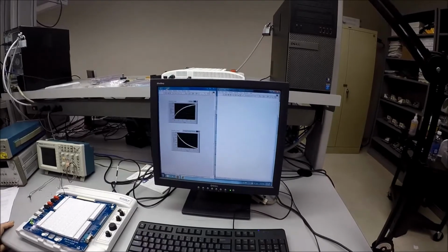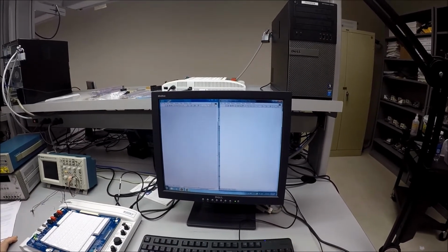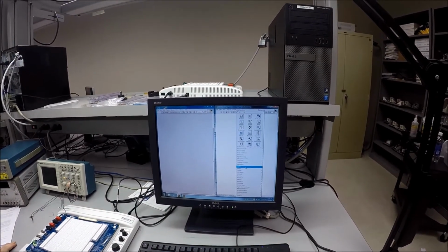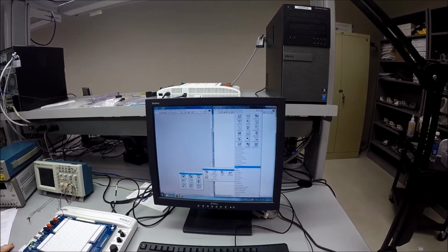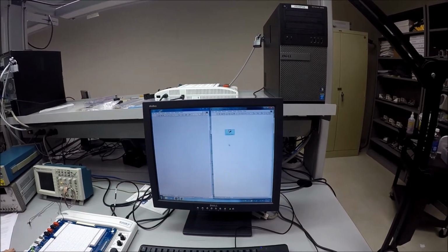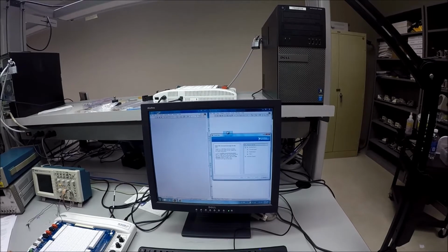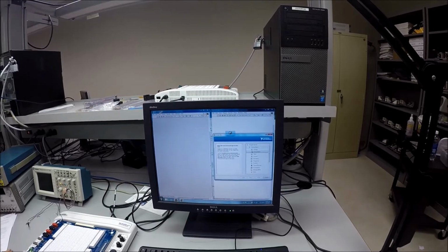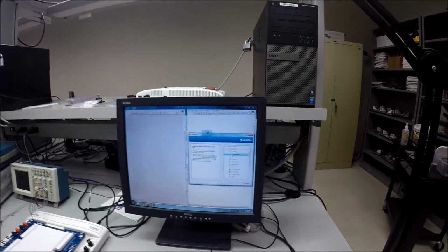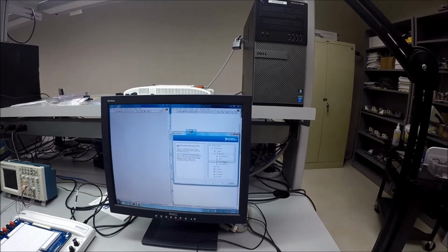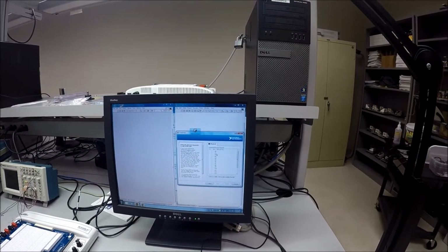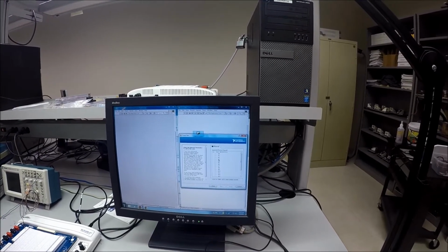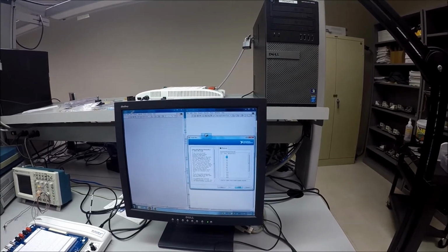And in the VI window, we delete them all, we don't need them. Again, go to Express menu, Input, DAQ Assistant. We want to acquire a signal, analog. This time we work with temperature directly, and we want it from the thermocouple. This time we are working with channel 1, AI1.